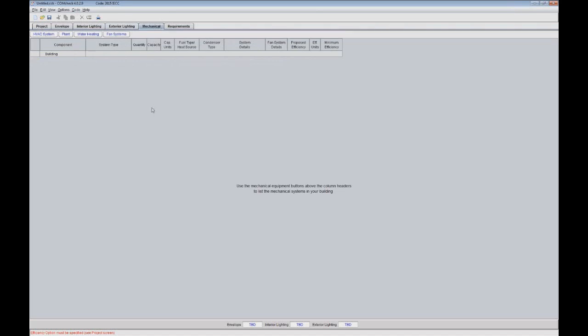And then we're going to finish this webinar with questions and answers right after I get through mechanical and the requirements tab. Mechanical does not give you a pass or fail. There is no compliance result at the bottom. But what it does do, it gives you a nice customized report, because depending on how much detail you have in your systems, the more information you're going to see that's going to be required to be entered. And what I mean by that is as you get into your fans, your supply, your exhaust fans, and you can enter those fans, and there is a little bit of calculation involved when you get to fans.